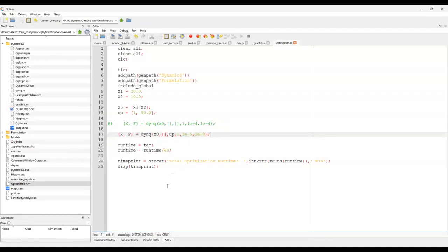So you say to start with no constraints and add things as you go. How would the optimizer run if it doesn't converge on a solution? Will it just stop? Yeah, so we're going to look at an example of that as well. I'm going to change the max speed value in the equality constraints to something like 2 meters per second. What you'll see is the optimizer is basically going to hang, so you're going to have a perceptible difference in the computation time between 2 consecutive iterations.